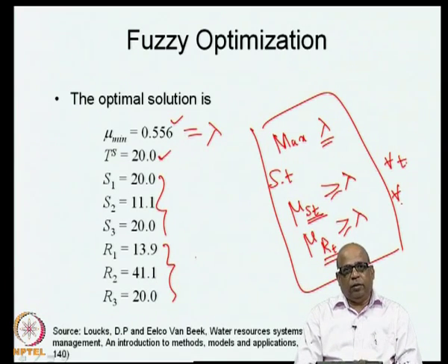So, essentially in today's lecture, we have continued our earlier discussion on the fuzzy optimization. We dealt with the water quality control problem and took a hypothetical example through which we demonstrated the use of the fuzzy membership functions, which indicate the conflict that exists in the system, and then we arrive at a best compromise solution when there are several stakeholders in the system, each with his or her own preferences of solutions, and these preferences often conflict with each other.